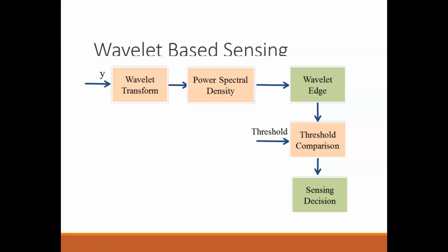One has the superposition of two components. Another signal has frequency 10 first, it stops, and frequency 12 comes then, for instance. If you apply the Fourier transform, both of them will have the same spectrum, isn't it? So the Fourier transform spectrum does not give you the time information. It tells you what all the frequency components present are, but that doesn't tell you when they come. So that is why we go for the short time Fourier transform, where you just take a small portion of it and, frame by frame or block by block, you apply the Fourier transform, which is referred to as the short time Fourier transform.